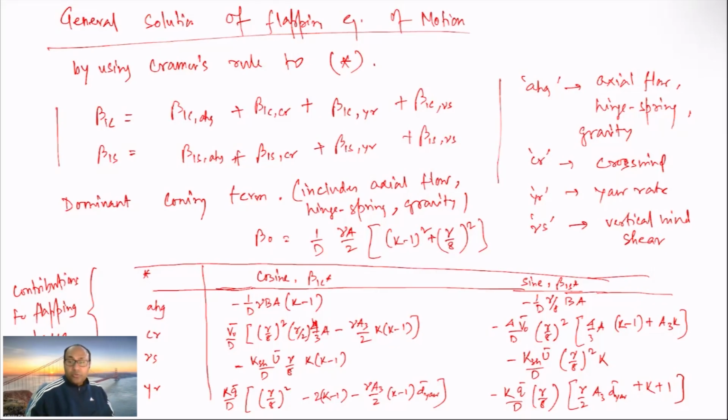But one important point to note here is that the various subscripted constants can help to illustrate the amount of response that is due to a particular input. For example, in a particular situation, if the wind shear sine cyclic response were close in magnitude to the total sine cyclic response constant, it would be immediately apparent from this system that the other factors were of little significance.